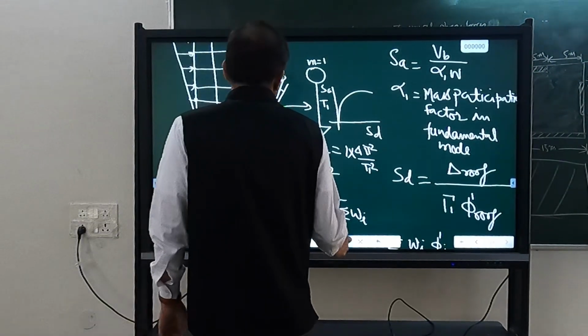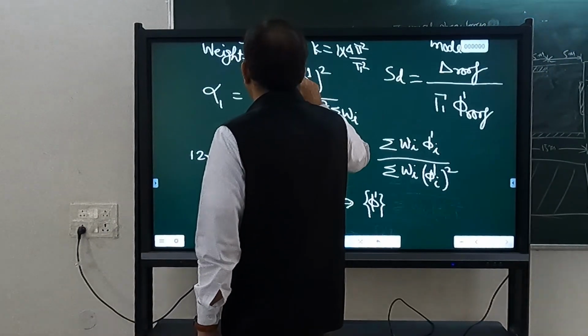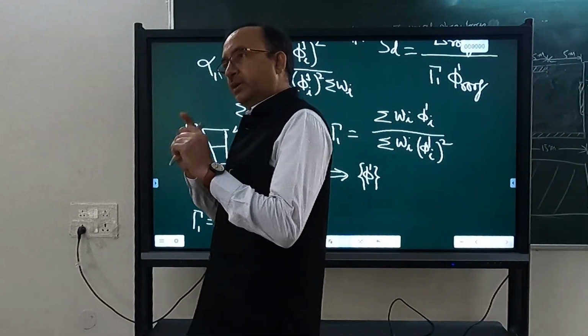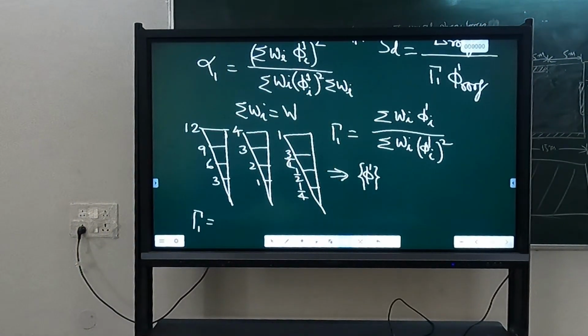Hidden capacity in terms of plastic hinges? No, hidden capacity in terms of characteristic strength, because you have used characteristic strength, whereas we are using expected strength. Secondly, we have used factors of safety while designing. Here we are not considering factors of safety.